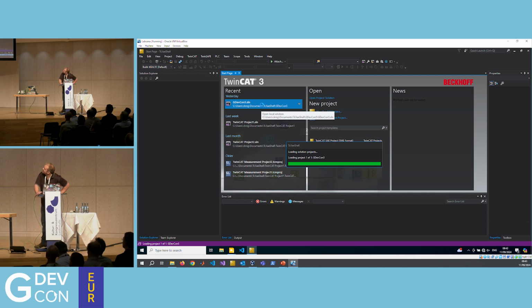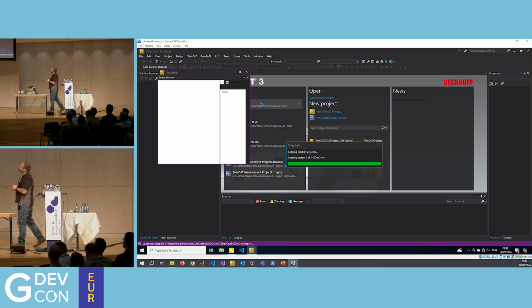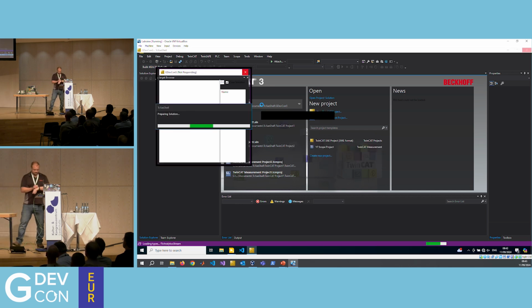So basically the TwinCAT system I'll show you now, this is obviously the TwinCAT Visual Studio-based engineering environment. All it's doing is running this EtherCAT network, basically. Well, actually, technically two separate networks. I have one network coming into this EK coupler here with some safety on it, which should be working. And I have another one running this bank of I/O over here.